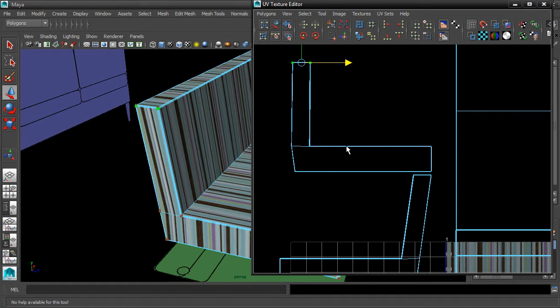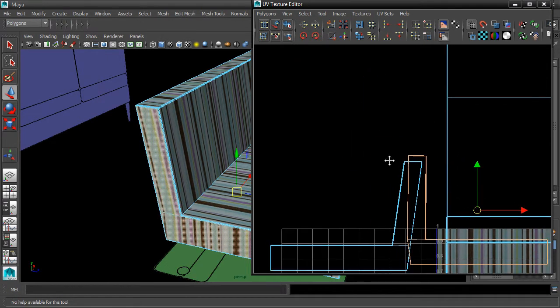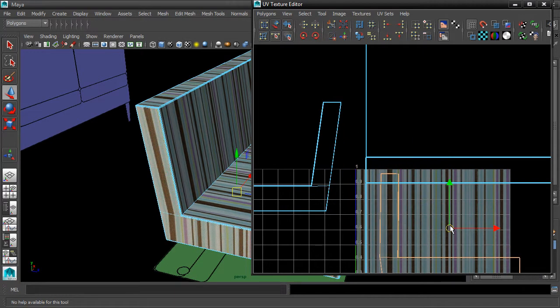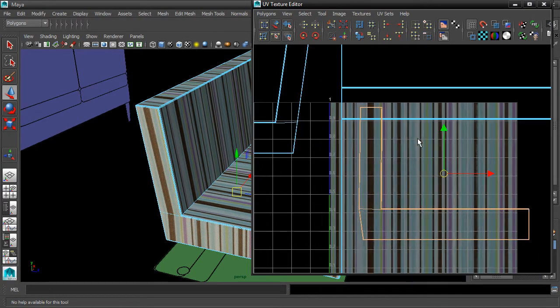It's even clearer if this is directly over the texture here. So I can move that whole shell. Right-click and go to Shell mode, move it over a bit. And we can see what we're doing a little bit more clearly here too. Right-click and go into UV component mode. So you can see how the placement here directly corresponds to the end result here. Just want to straighten this out and make it into more of an L shape here in the UV layout.